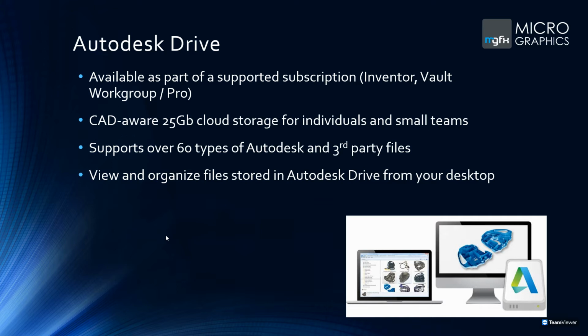Okay, so Autodesk Drive. What is Autodesk Drive? Autodesk Drive is sort of like a little cloud storage unit, which is CAD aware. And when I say CAD aware, what I mean is that in Inventor you've got child and parent relationships. For instance, if you've got your Inventor assembly, that would be the parent, and the children would be other sub-assemblies sitting inside that assembly, or the parts that you've put in there connected together to create that assembly. And an assembly could be a child of a drawing file, a 2D drawing file where you get your front view, your side view, your isometrics, any detailing. So the drawing file would be your parent, and then the assembly would be your child.